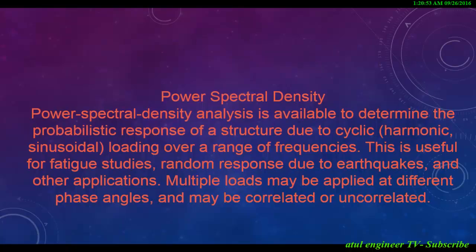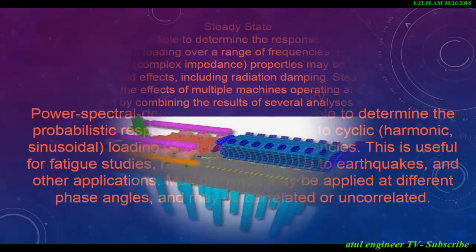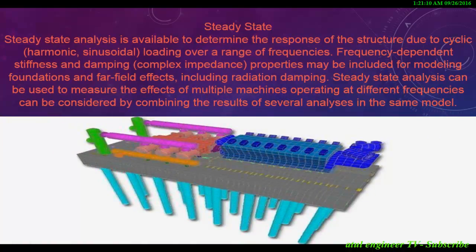Power spectral density. Power spectral density analysis is available to determine the probabilistic response of a structure due to cyclic, harmonic, sinusoidal loading over a range of frequencies. This is useful for fatigue studies, random response due to earthquakes, and other applications. Multiple loads may be applied at different phase angles, and may be correlated or uncorrelated.